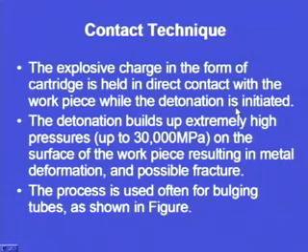Whenever we cause a detonation, the explosive in the form of a cartridge is in direct contact with the workpiece that we are going to plastically deform. In case of the standoff technique, there was a distance between the workpiece and the explosive charge, called the standoff distance. Here there is no distance; the cartridge is in direct contact with the workpiece material. The detonation builds up extremely high pressure.